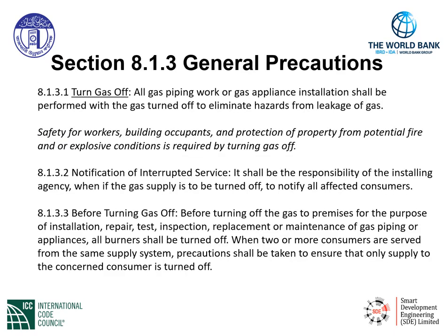In Section 8.1.3, General Precautions, we have further information to go over to completely understand what we need to do with respect to any precautionary measures when we work on or install the gas piping system. Section 8.1.3.1 is titled Turn Gas Off. All gas piping work or gas appliance installation shall be performed with the gas turned off to eliminate hazards from leakage of gas.